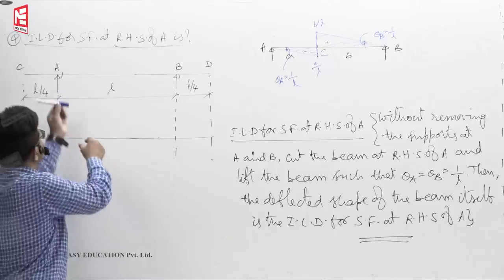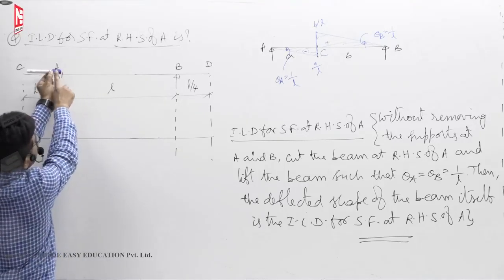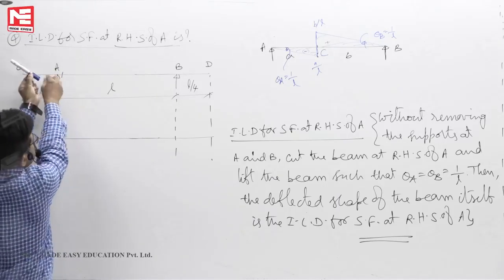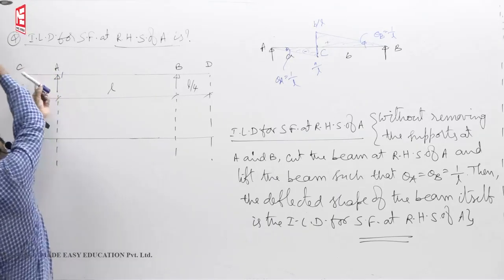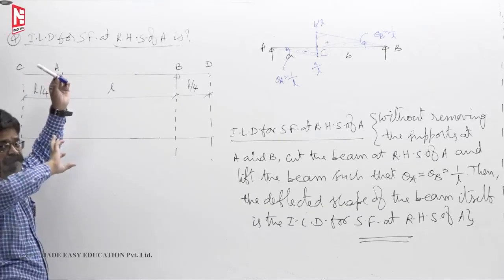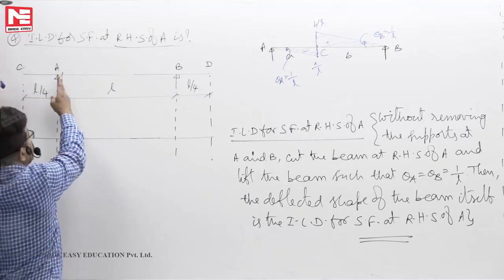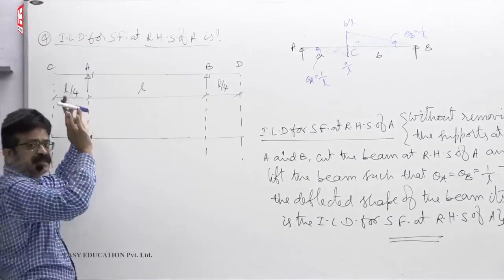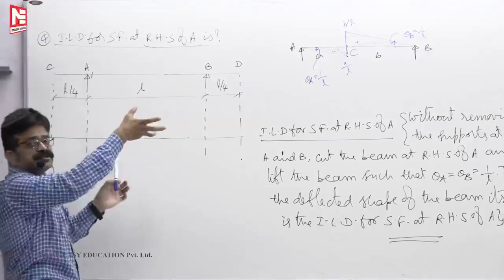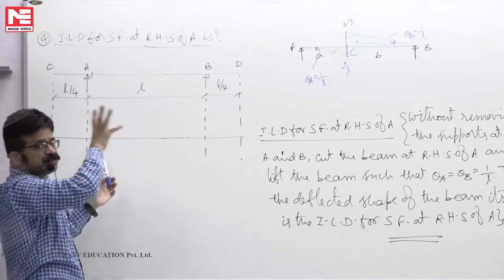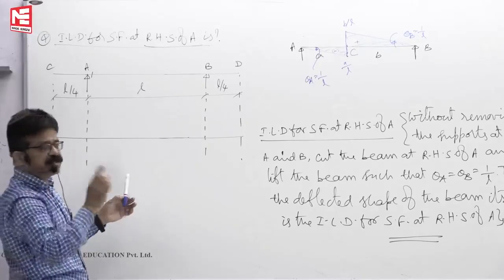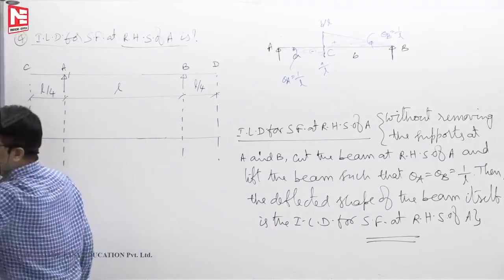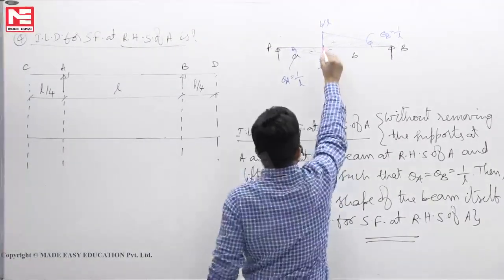So rotate clockwise. However small it is, if I rotate this small piece clockwise like this, if the overhang is not there, no issue, only this will come down. If the overhang is there, it will go up. Let it go up. You wouldn't bend, you wouldn't break. Once you cut this beam, it becomes unstable. That unstable structure, if I rotate, undergoes only rigid body rotation. So no curves will be there, only straight lines should be drawn.